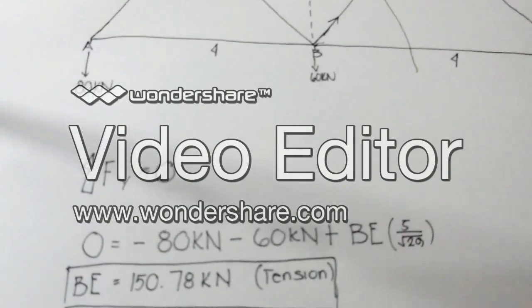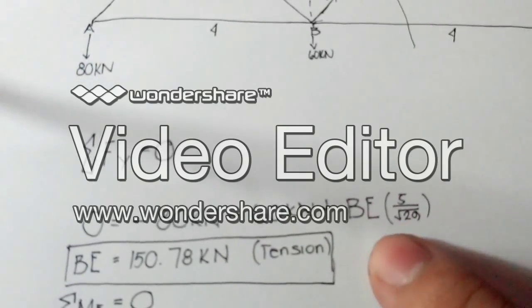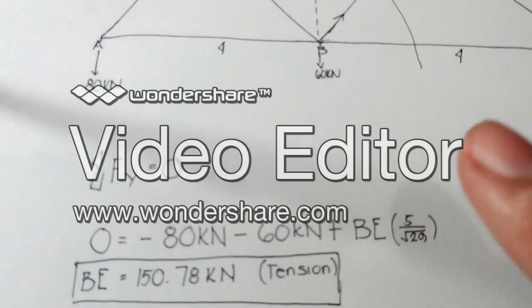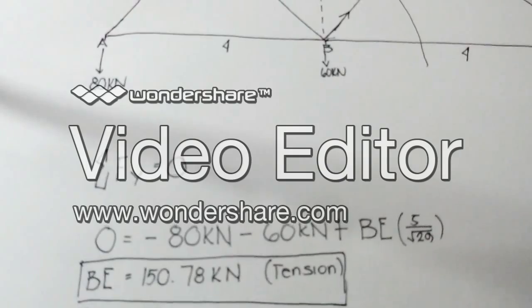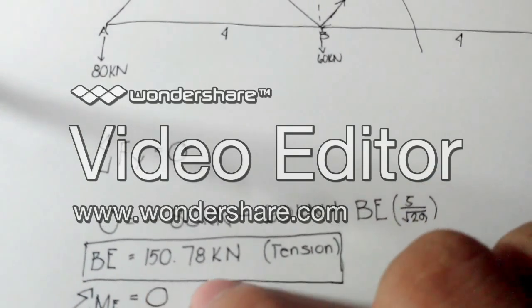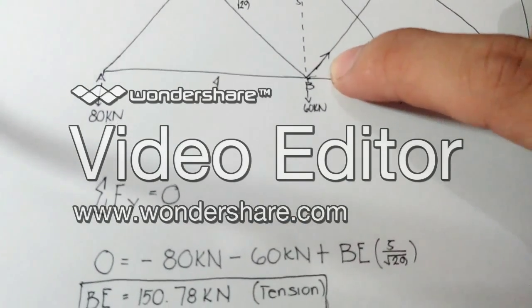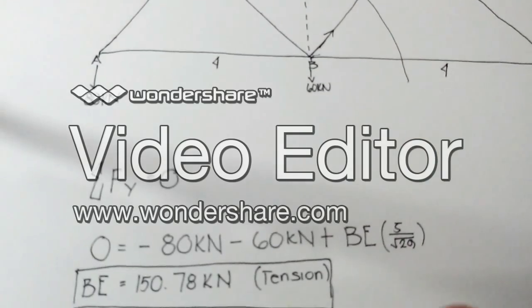So here, back to the equation. BE multiplied by sine theta, which is 5 over square root of 29. So solving the problem, BE is equal to 158.78 kilonewton. Since it is going away from B, it is tension.